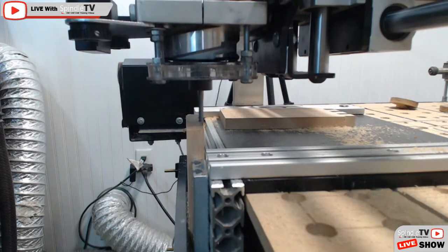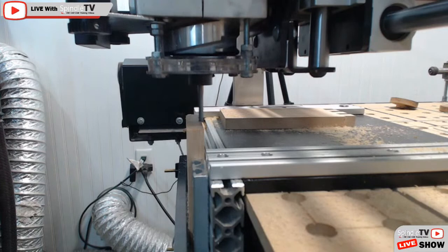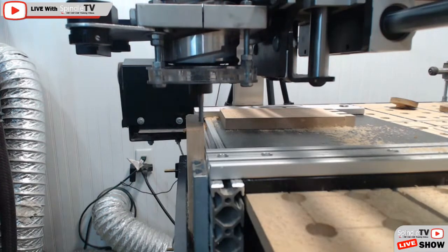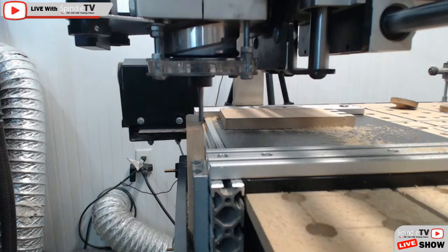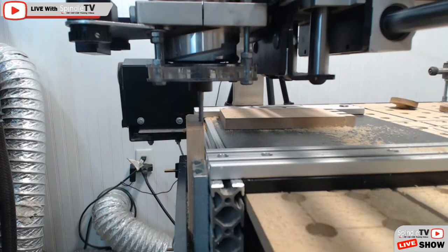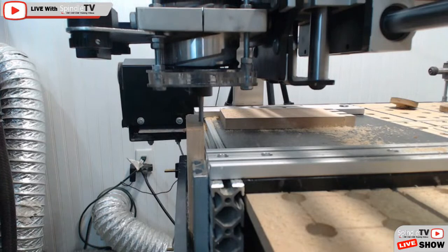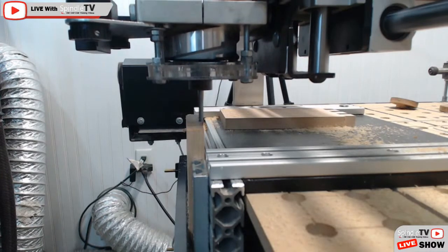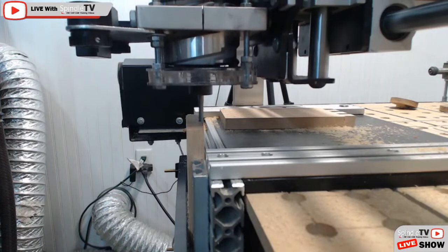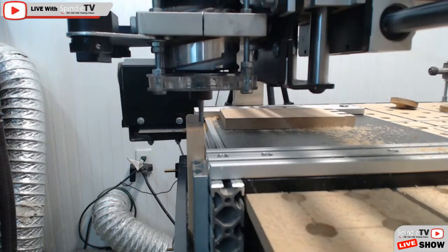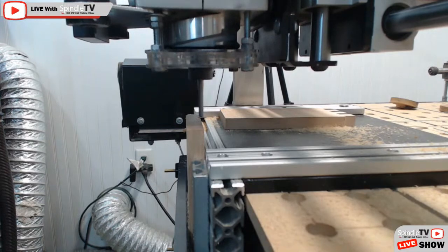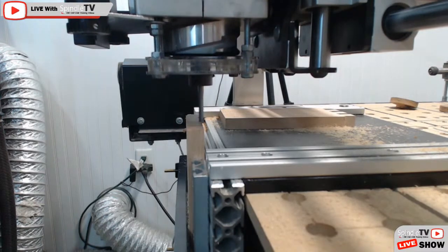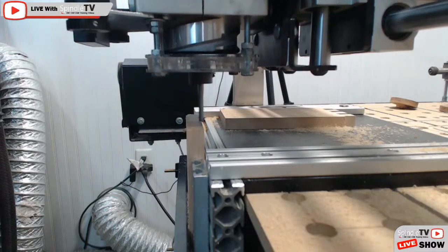It's drilling down and relieving the waste on those edges to help reduce tear out. I'm using an upcut spiral bit. The upcut spiral bit will pull those fibers up because it is on the vertical, versus a downcut spiral, which would be pushing them down. And I don't want to push them down because that would cause more tear out in this vertical instance.